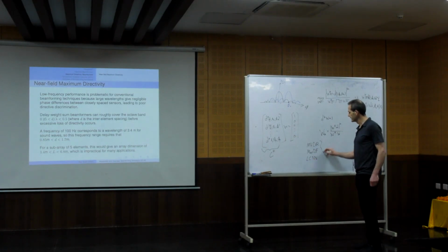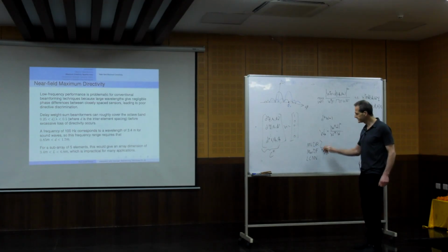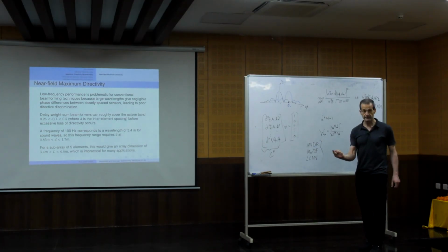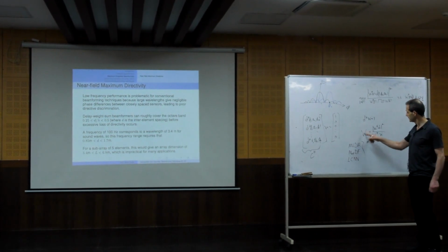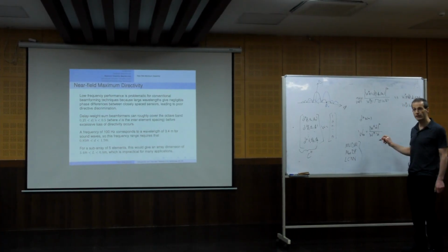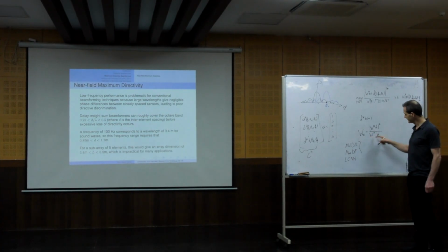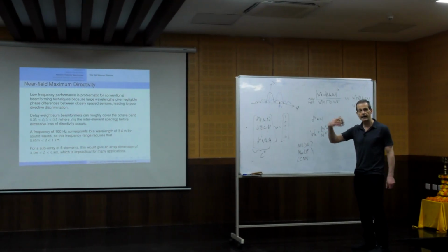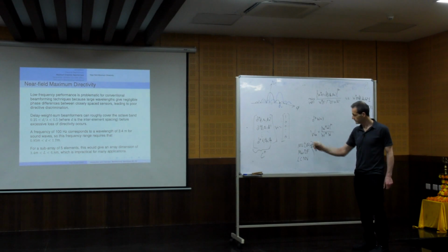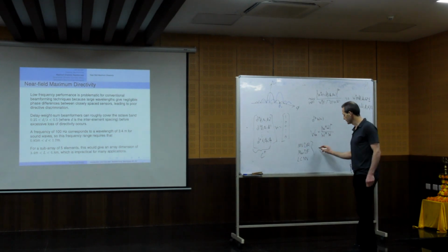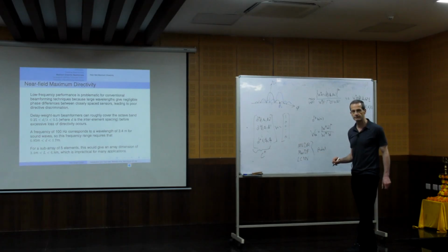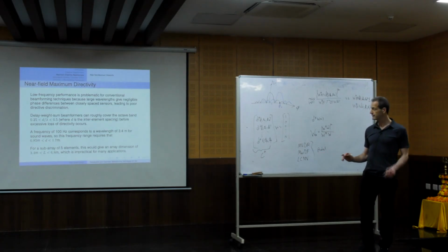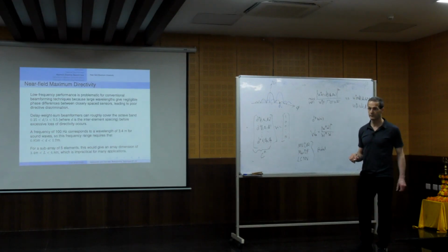And for all this, and actually we have more beamformers, for all this, we can add an additional constraint that the white noise gain will be higher than a certain threshold. If we add the constraint that the white noise gain will be higher than a certain threshold, all this will be robust. So we call robust MVDR, robust max DF, robust LCMV. Okay? Understand that? We have additional beamformers.